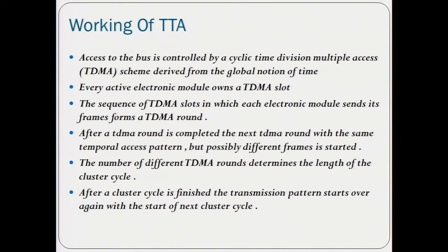And so, in fact, this way of thinking about communication and computation is called a cyclic schedule. So everybody gets their own time, and that is fixed forever within the interval of time that is dedicated to the round of polling of the various nodes.